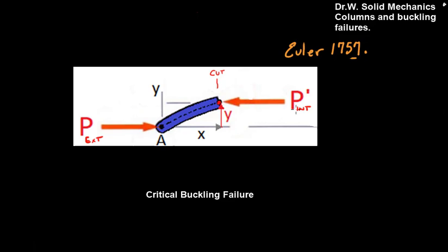And summing the forces in the X direction, we can see that they'd be the same magnitude. And they're offset by a distance y, which is creating a couple in this direction. Therefore, we're going to have an internal moment here of negative Py, where that's the force P and y is the distance away, and it's a negative moment because it's concave down.